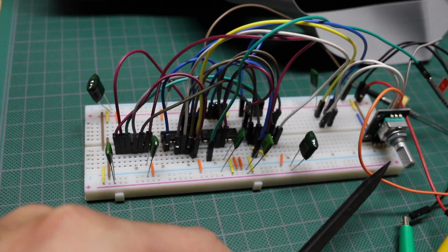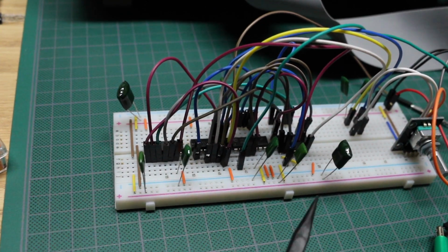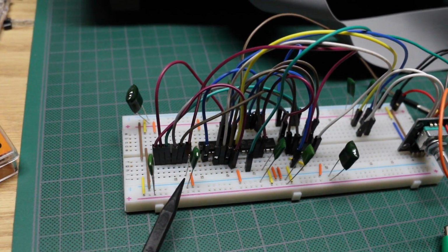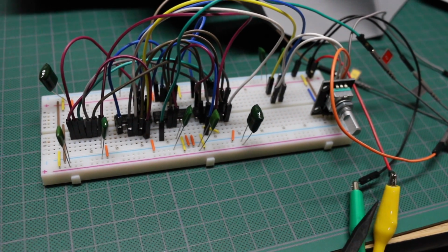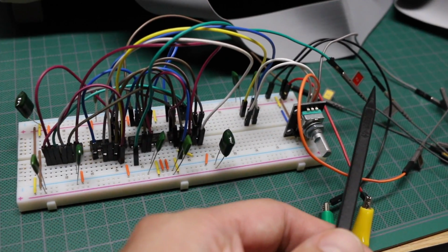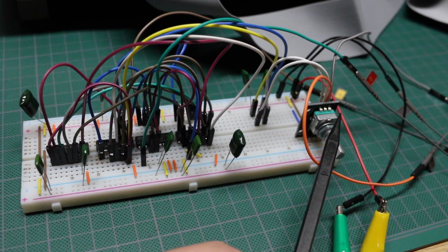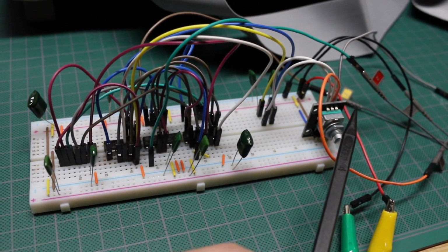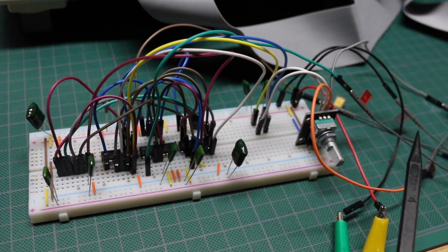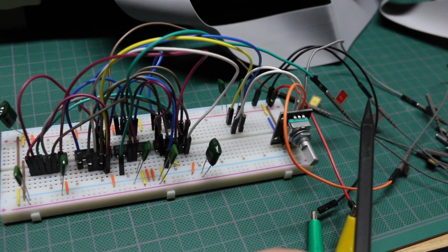I have the rotary encoder over here on the end, the logic circuit here, various decoupling capacitors and filters. I put one on a reset pin here because it was really noisy. I have 5 volts coming in here from a bench power supply, and all the inputs and outputs tapping into the Rigol scope's logic analyzer input. So the two A and B outputs are going into the circuit to be processed, as well as off to the logic analyzer, and then the output of the logic circuit is going to the logic analyzer.